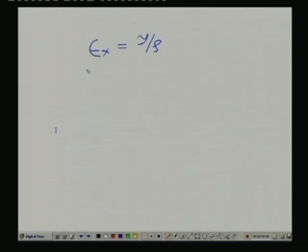So, what is the stress? Sigma equals E into epsilon x, which comes out to be E y by rho. So, we can see that for a given bending moment, E and rho are constant, so the stress varies with the distance y from the neutral axis.